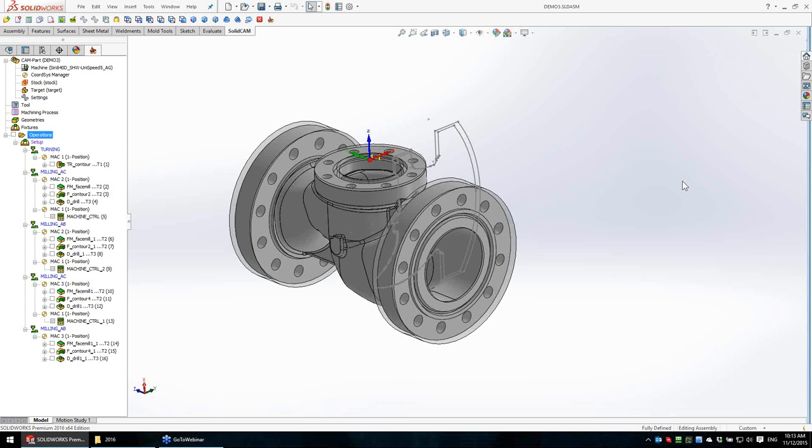Okay, Florin, next question. Is it possible to move the part from a milling machine to a turning machine with updated stock? Milling machine to a turning, no. If you move a mill-turn to a mill-turn, yes, but not milling to turning. You cannot change a milling part to a turning machine, because in a turning machine you don't have milling, so what do you do with all the milling operations? So maybe he means from a milling machine to a mill-turn machine.